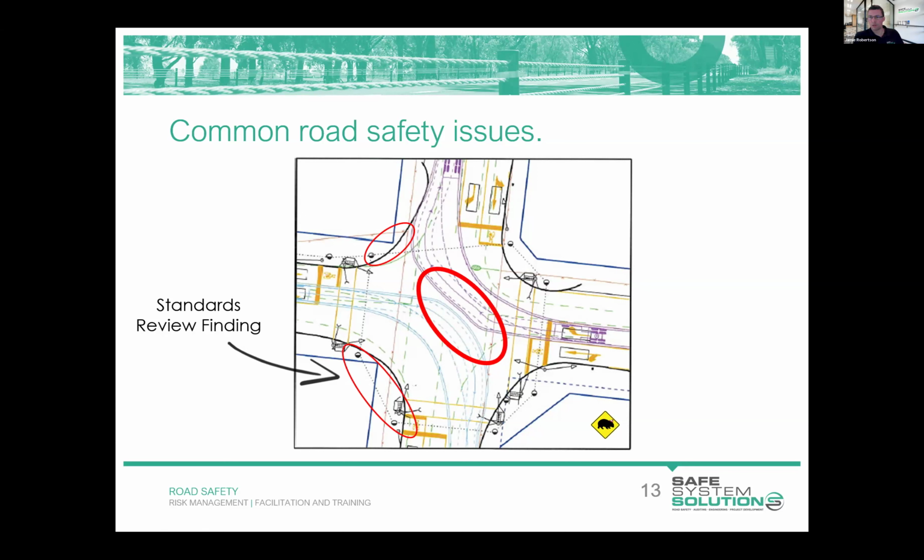If it's a mandatory stop situation, you'll use a lower speed than a situation where you might arrive at a green light and not have to stop, or a give-way situation where you wouldn't necessarily have to stop. So Austroads gives that guidance. The lower the speed, the greater the swept path width. So there are benefits in generating these diagrams at a higher speed, so you have to be careful that people are doing things appropriately.